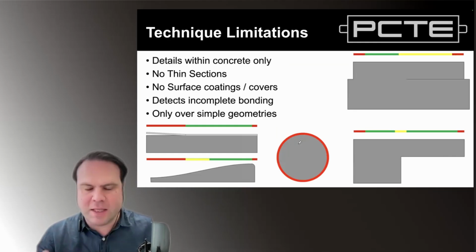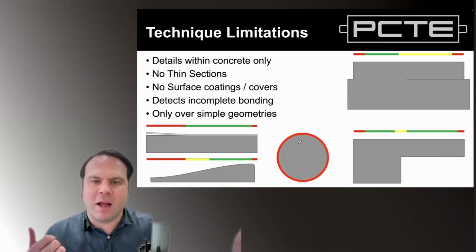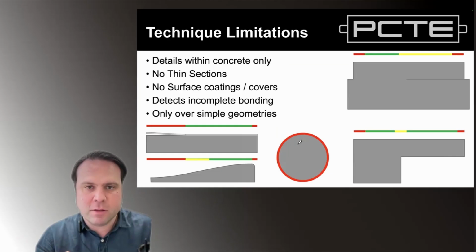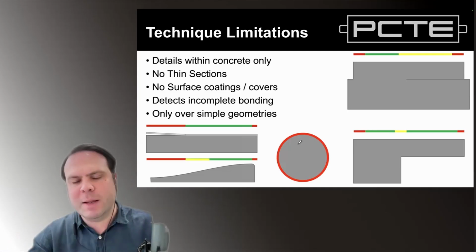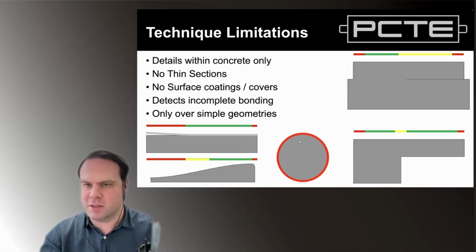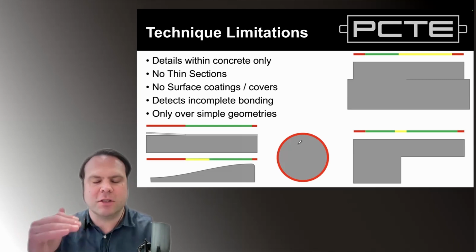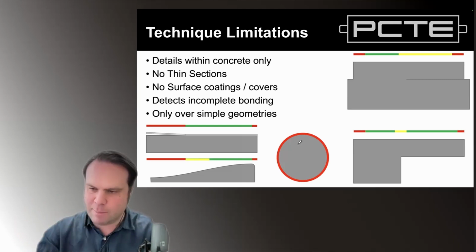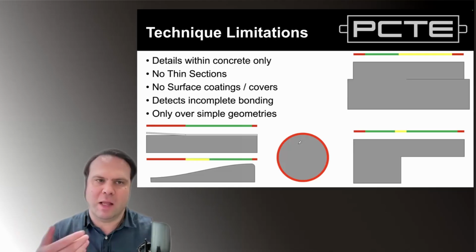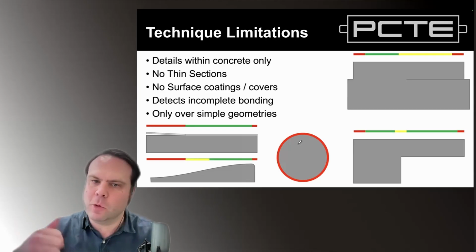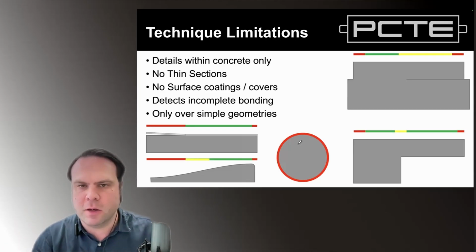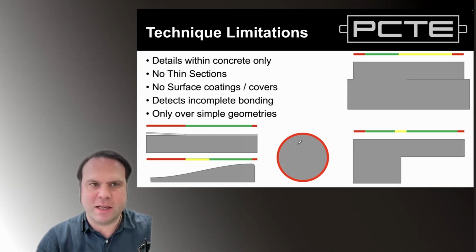So first thing, by within the concrete, I mean, if you have a slab on ground and you have a suspended slab, because of the way we filter and how we take the data, an impact echo test with its filtering and processing and collection, they will functionally look the same. So a thickness test of a slab on ground and a thickness test of a suspended slab with impact echo will have the same result. We're not able to tell anything about the support conditions, the subground conditions of concrete with impact echo.